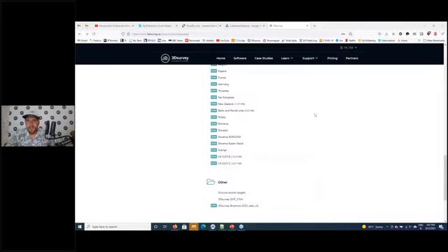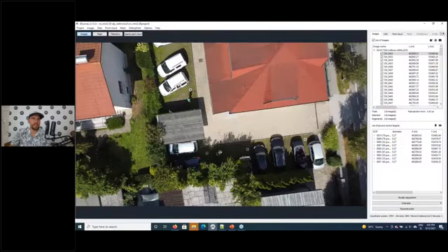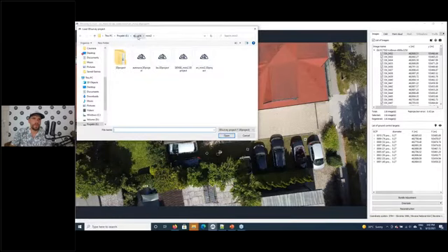Okay. And the final question today: the difference between the LiDAR and drone survey is systematic. I mean, if you fly at 30 meters, it will always be 6 to 7 centimeters or above. So in this example that we had here, the difference was systematic, yes.